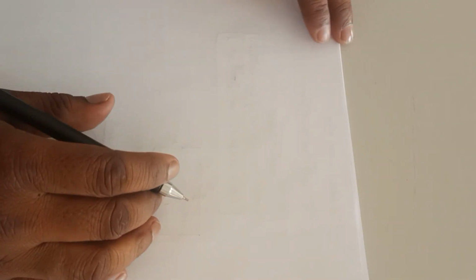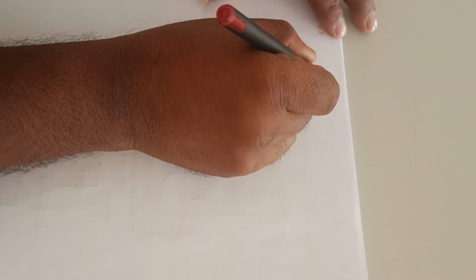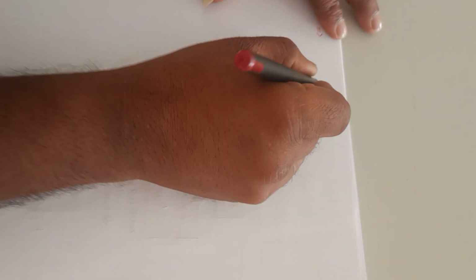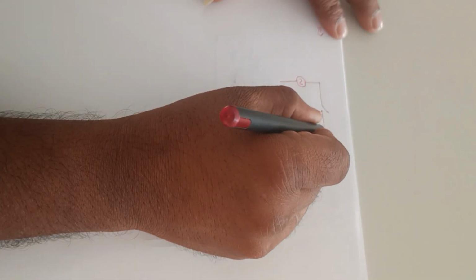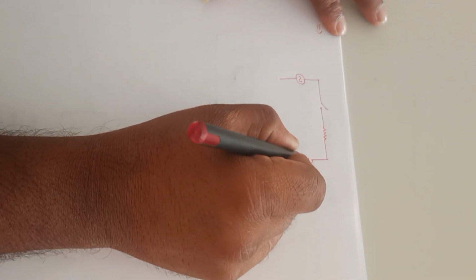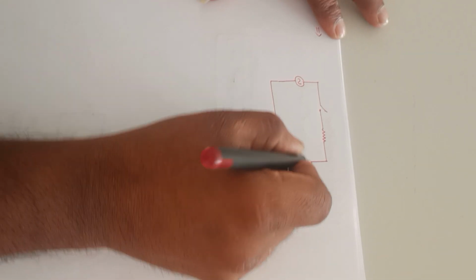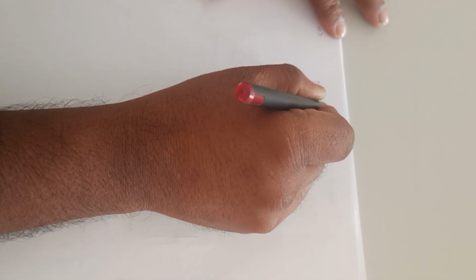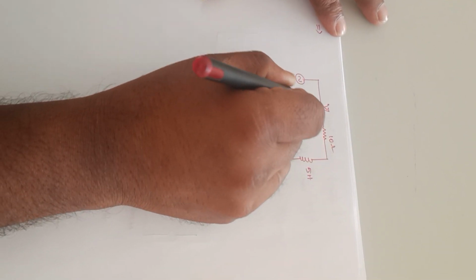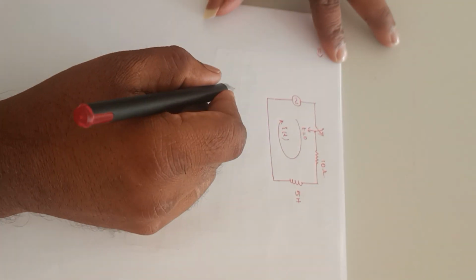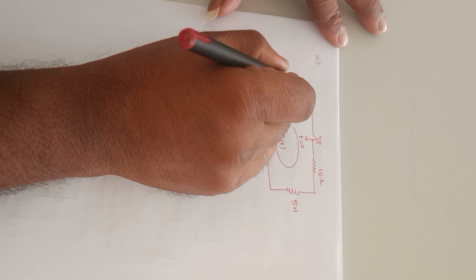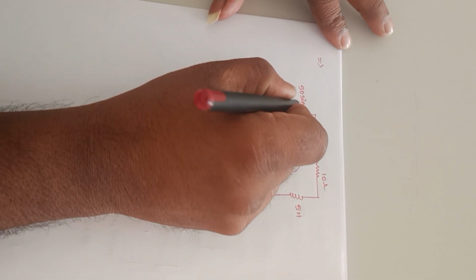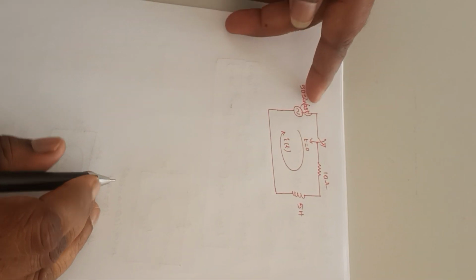Another problem on this RL circuit itself, a different problem. Here this is the sinusoidal input. Now we are giving a sinusoidal input. It is an RL circuit. This value is 5 Henry, this value is 10 ohms, and the switch was closed at t is equal to 0. This is the current I of t and the input for this is 50 sin 25t. So this is the excitation input for this RL circuit.